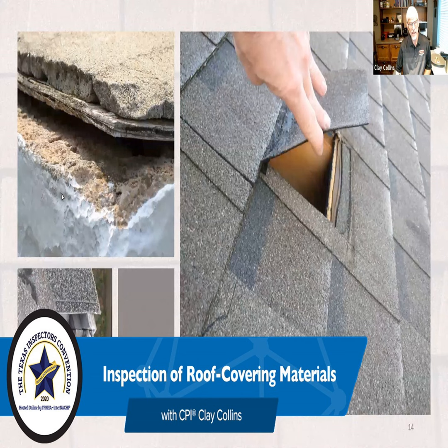But if you look at some roofs where you have some part of it that has tree covering and some part of it doesn't, you see algae growth under the areas that have no UV rays. So even though the UV rays might cause damage, if the shingle's properly designed and manufactured, those UV rays should not be a real problem.